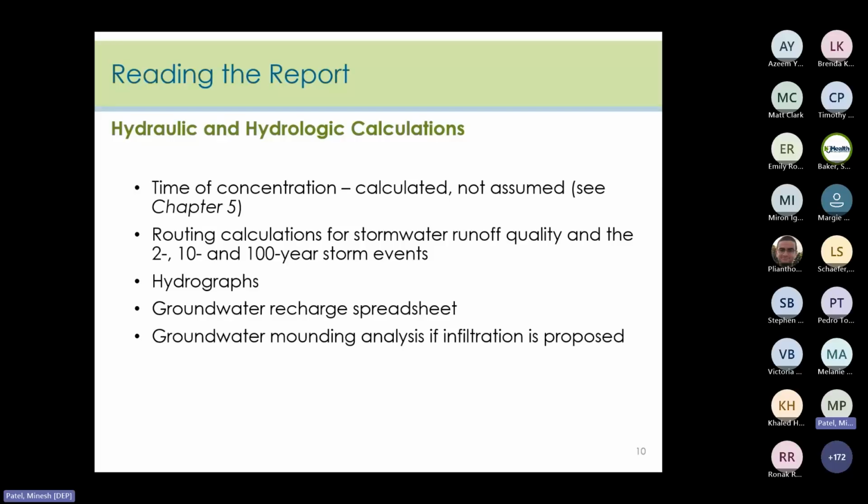No matter the format, though, it is important to include all of this information, including storm routings, hydrographs, the groundwater recharge spreadsheet, mounding analysis if it's applicable, and water quality calculations, and make sure it actually matches what's on the plans.